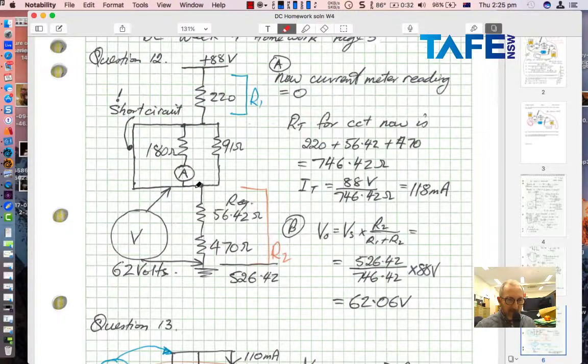And that would be a bit of a mess, because if the meter had an internal resistance of like 20 ohms, because it's only a milliamp meter, so it could have a fair bit of resistance, then that 20 ohms would be in parallel with 91 ohms, and that would give me some really weird reading across that. If you put it like that, it would become what they call a shunt resistor across the ammeter, and that'd be a really weird thing to think about. So yes, I did make a small mistake there. I went across the whole network, and it is worth thinking about that.